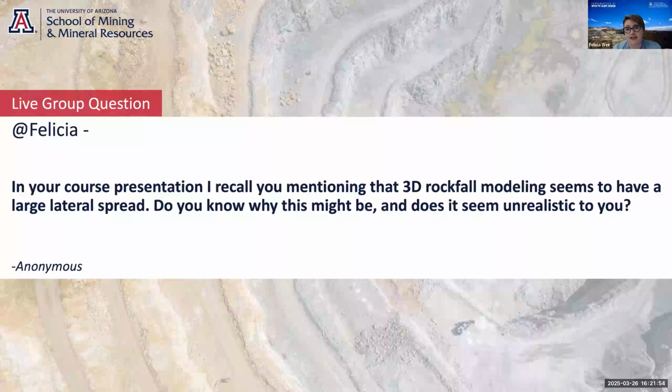And if you're doing a design cutback and you put in a smooth surface, a lot of the 3D rockfall modeling doesn't then account for surface roughness. So just be very careful. It's something we've had to start building in roughness into some of the 3D surfaces that we're analyzing.